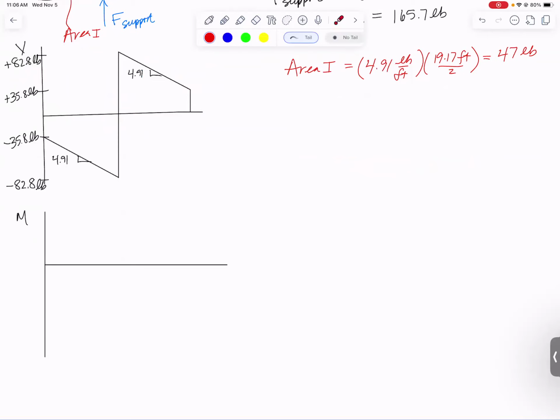What's the bending moment diagram going to look like? We expect it to be symmetric because our beam is symmetric. We are going to start with a negative slope, and that negative slope is just going to get more and more negative, starting with a negative slope, but ending up with a much more negative slope with a parabola. Then all of a sudden our slope switches signs. So we're going to have a cusp and we're going to go back up kind of like that. And what matters for this diagram is M max. We need to figure out how big it is.